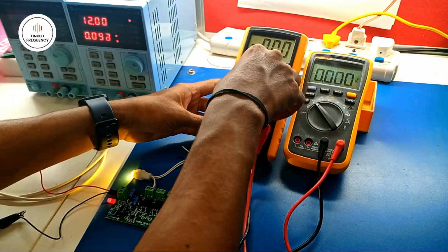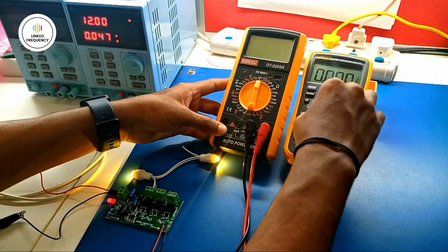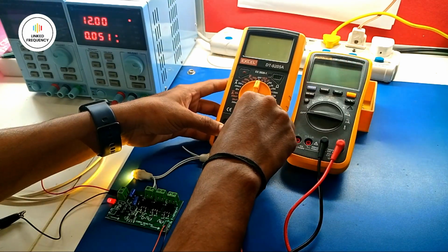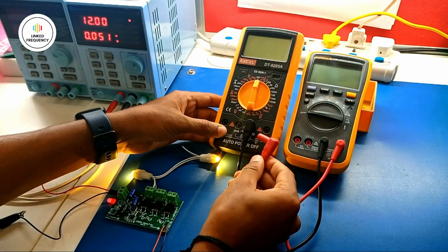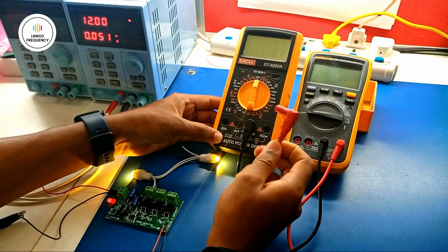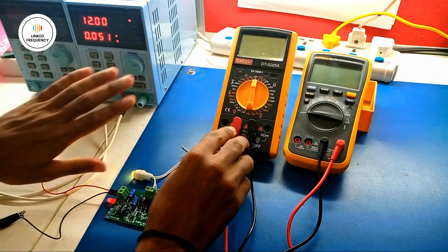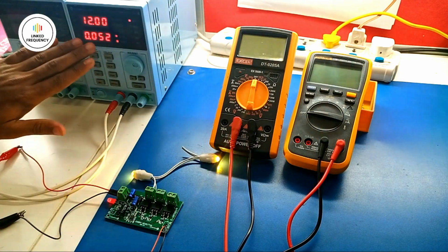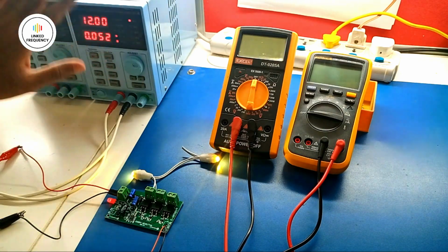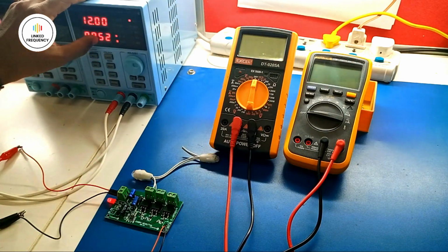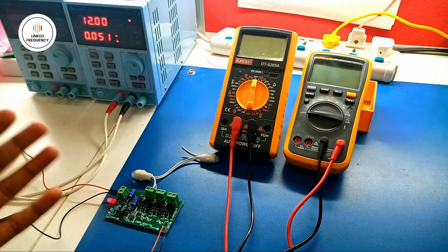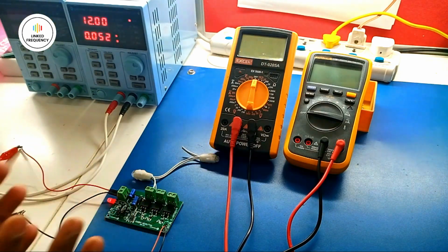First of all, I'm going to turn off both multimeters, and then unplug the voltage probe, or maybe the positive probe, of the multimeter and place it in the milliampere socket. Why? Because we know that this particular circuit is consuming less than 100 milliampere through this power supply indicator, and since we designed this hardware, we know its power consumption.